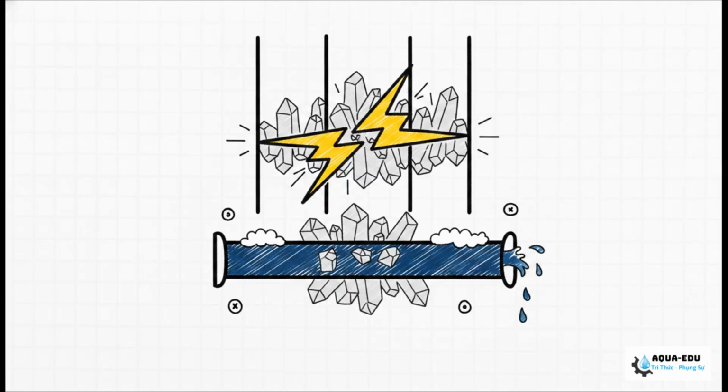But beyond just the scary numbers on your screen, you've got a physical nightmare happening inside: hard scaling. Calcium, magnesium, and polymerized silica are actually precipitating directly onto your resins and membranes. And what makes this so incredibly destructive is that this scale acts as an electrical insulator. Remember that vital DC current we need for water splitting? The scale blocks it completely. You're going to see increased electrical resistance on the module, and eventually that scale will physically choke the internal channels, crushing your product water flow.